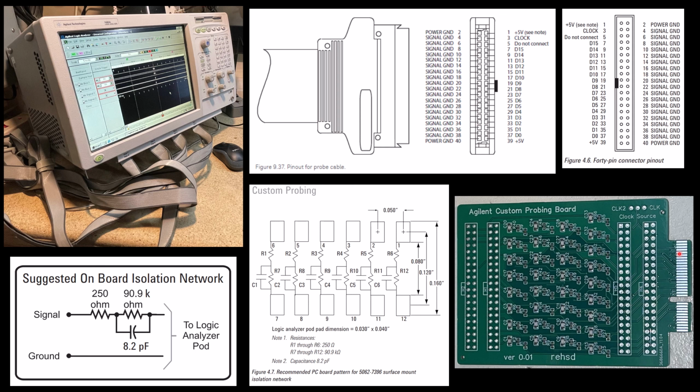If you notice these headers, these are simply headers that connect to the same signals off of the PCI Express. So either I can use them as quick test points to see what's coming through the PCI port, or I can disconnect this from the debug header on my 386 and just directly connect signals to these pins to get them through this isolation network over to the logic analyzer.